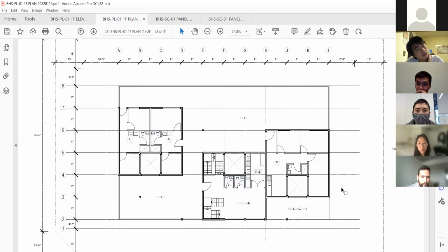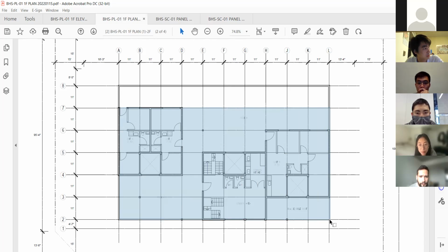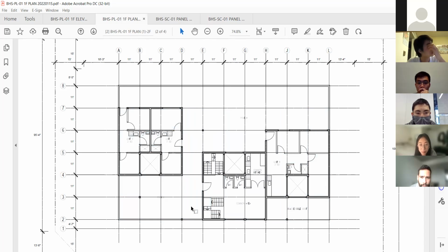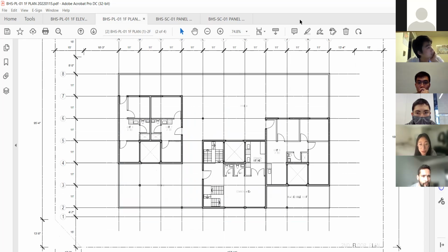It isn't worth it to have the insulated material for a podium, because a podium is just a rain shelter, the kind of thing. Yeah. The podium, the deck doesn't have to have insulation. So the separating line can be the column, if you draw a horizontal line across right there. Beyond the column point will have no insulation, and below that column there will be insulation because it's going to be the first floor. Yeah, that transition works, logical.